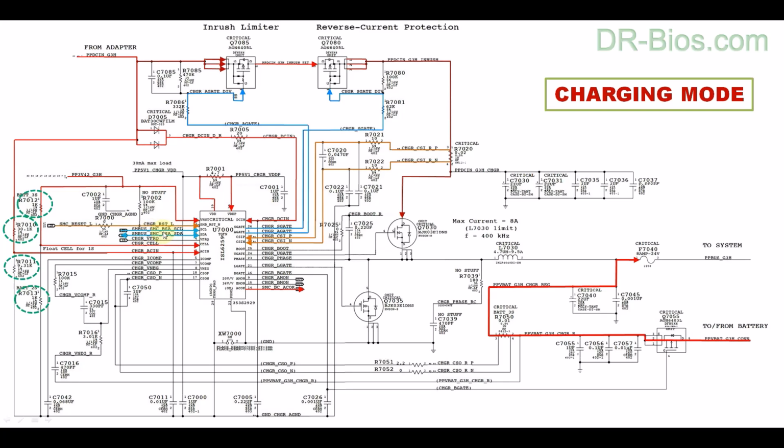At that moment, SMC shares the data with IC. The data SMC received from battery through SMBus protocol informs about the battery status, whether it needs to be charged or not. If yes, how should the battery get charged? According to this information, charging IC drives MOSFETs with PWM technology in a way that it provides the voltage needed at that moment for the battery. And after providing the voltage, by driving the controlling MOSFET of the battery, it lets battery use the provided voltage.